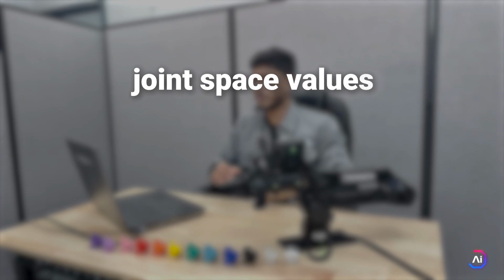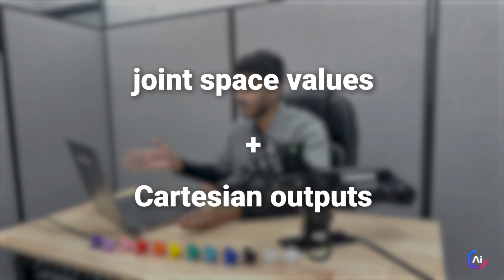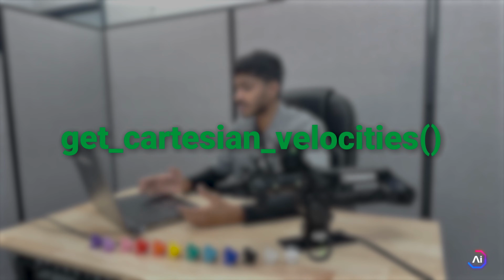In addition to joint space values, we also have Cartesian outputs. So if you are working in a tool space like controlling the end effector or monitoring its movement, you can use the get_cartesian methods. For example, get_cartesian_positions, velocities, or external efforts. All of these follow the same naming structure, so once you get used to one, the rest of them are easy to pick up. This really simplifies the logging, diagnostics, and control logic of your code, and makes the API really intuitive to work with.